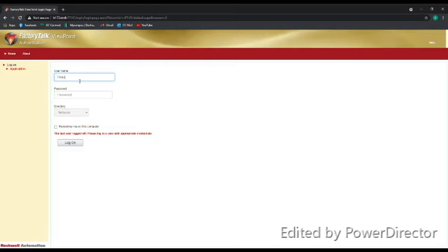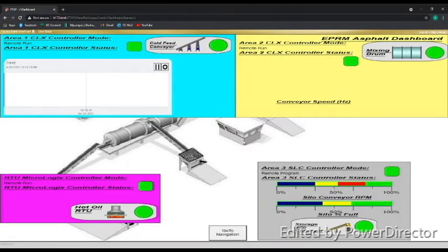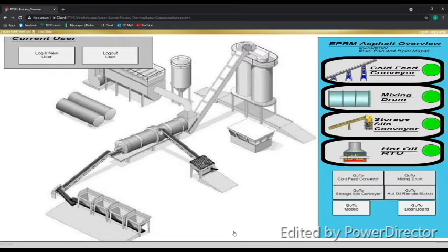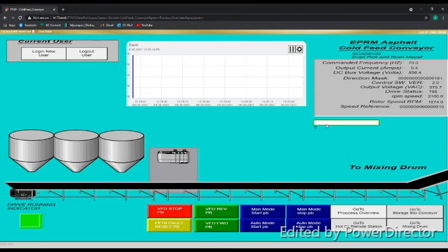So I'm going to log in with the Bo username that I created under the evaluation user group. Same password as everything else, but this is just to show that there is only write access to the area 1 display and everything else cannot be written to. So as you can see on area 1 here, I can punch in a value of 65 Hertz, run the VFD reverse, press the auto start PB. It's going 65 Hertz backwards.